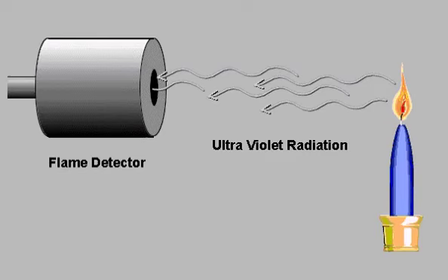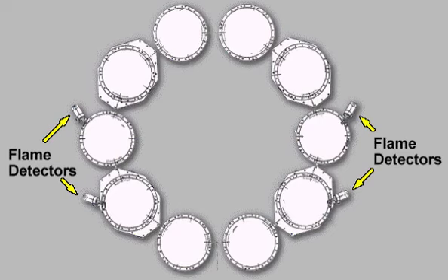The flame detector system, used with the Speedtronic system, detects flame by sensing ultraviolet radiation. Such radiation results from the combustion of hydrocarbon fuels and is more reliably detected than visible light, which varies in color and intensity. On non-DLN units, the flame detection system typically consists of 2 to 4 independent detectors per set of interconnected combustion chambers. Please click on Back to continue.